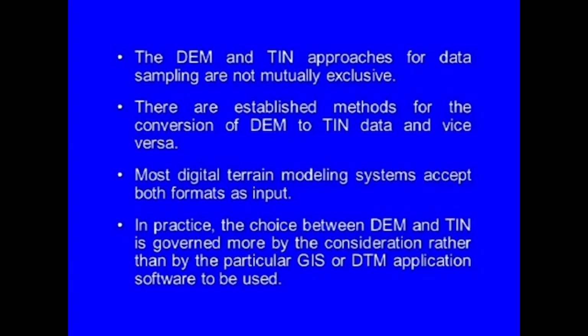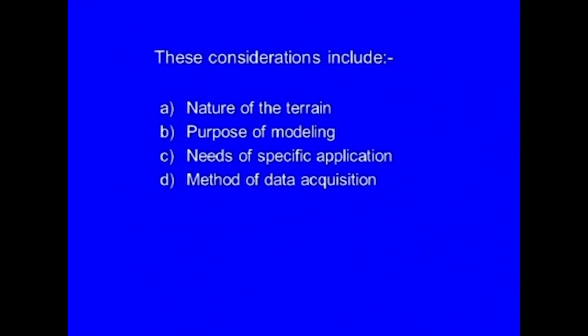In practice, the choice between DEM and TIN is governed more by other considerations rather than by the particular GIS or DTM application software to be used. These considerations include the nature of the terrain, the purpose of modeling, needs of specific applications and method of data acquisition. So, let us look at these considerations one by one.